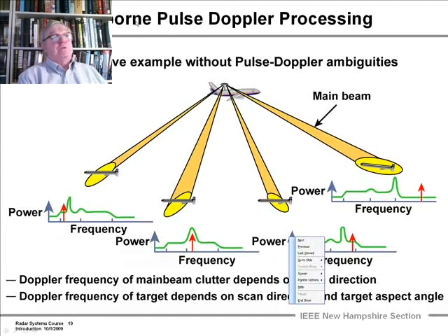Now, this is to show you that adaptive processing is tough. And the reason it's tough is if you look at the clutter, if you have on a radar, on a plane, a rotating antenna, and the main beam is pointed in this direction, which is to be forward, and we have a cruise missile here, this is the target, coming in at you. Here will be the main beam, which will be hitting the ground if it's in front of you at this point, and the Doppler of the target is such that you'll be competing against receiver noise.